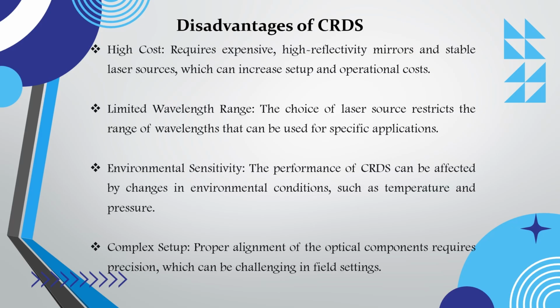Third is environmental sensitivity. The performance of CRDS can be affected by change in environmental conditions, which is temperature and pressure. Fourth is complex setup. Proper alignment of the optical components requires precision, which can be challenging in field areas.